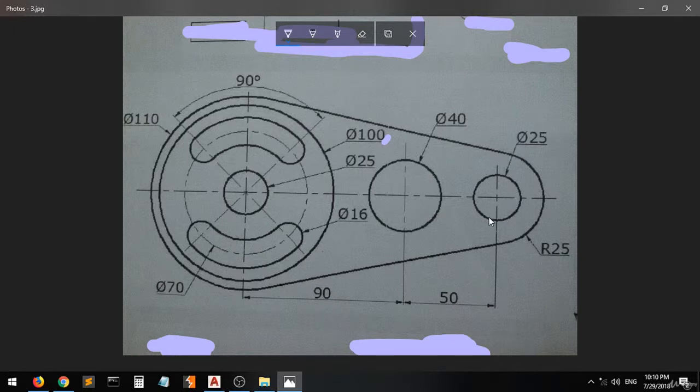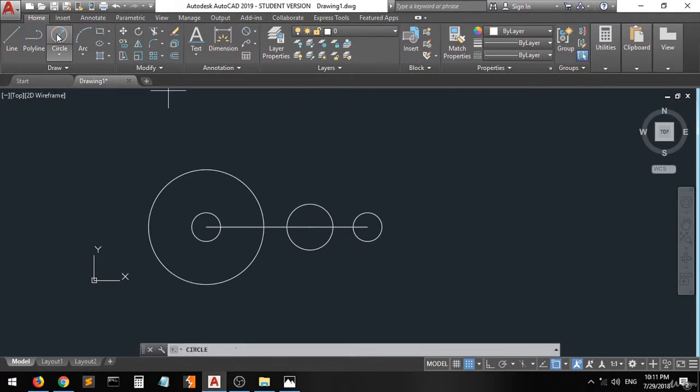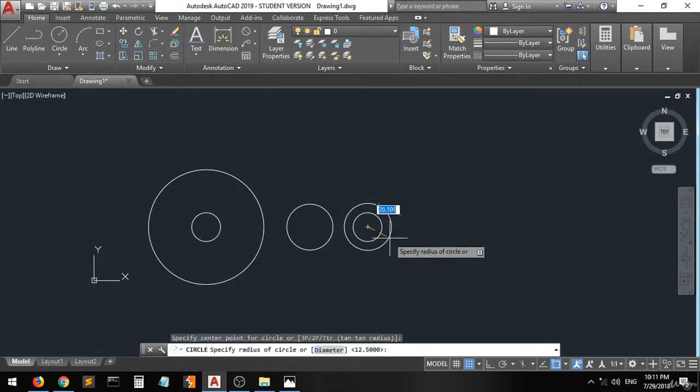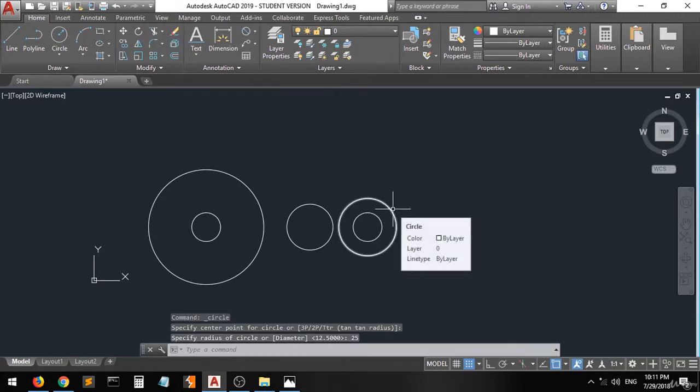Now this is really good. As you can see, we have some kind of circle, and it's trimmed from this. It looks like a whole circle, but this part is trimmed. So we'll just draw a circle, the radius of 25, and we'll trim this part, okay? So let's go. Go to the circle from the same center. First of all, let's just delete these lines because they are just guiding lines. We don't need them. Go to the circle command here. But now we will type R for radius. Enter. Let's put 25. Enter.